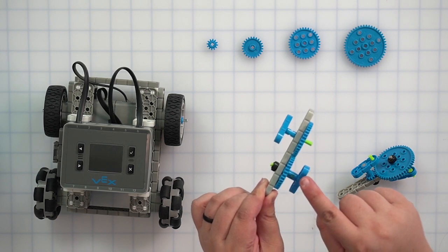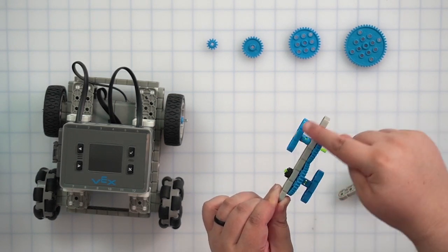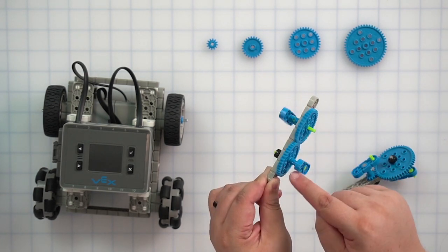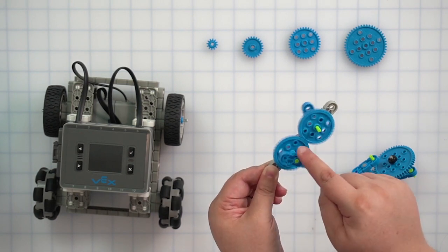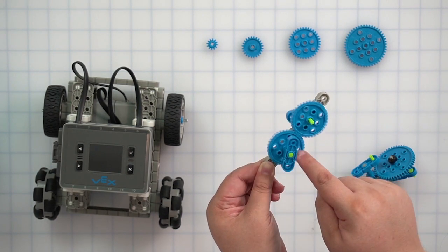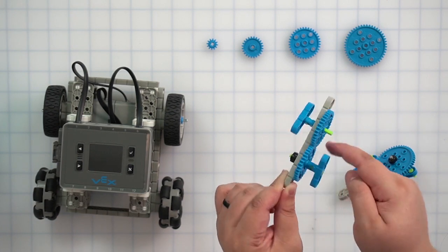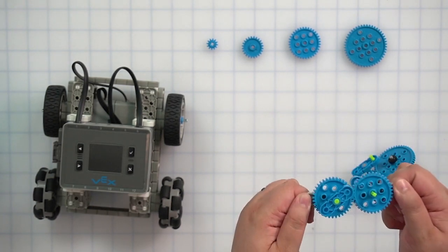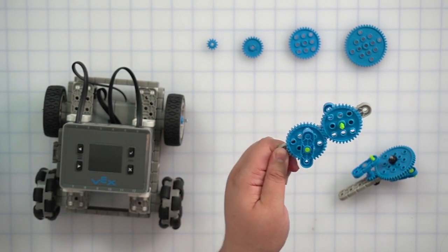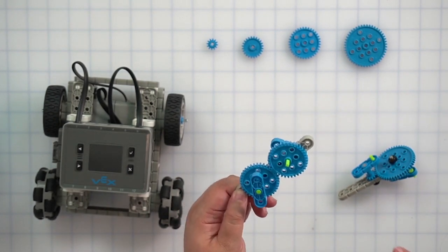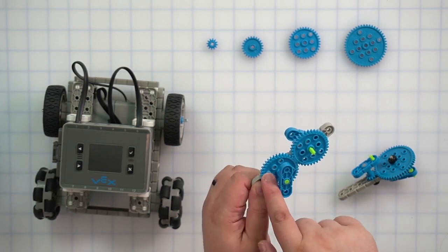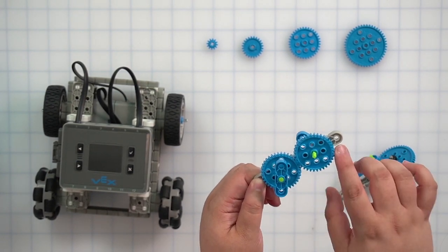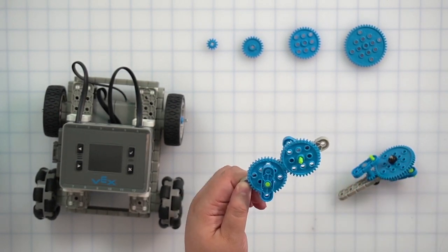If I spin this piece, this will be my input, this will be the output, so driving, driven. If you watch, the gears are spinning opposite of one another. My input gear is spinning clockwise. My output gear is spinning counterclockwise, or vice versa. That's if you want to change the direction of your output force. There's no mechanical advantage here, just direction. And because it's the same number of teeth for input and output, this is classified as a 1-to-1, because your ratio is the same, 36 to 36, so 1-to-1.